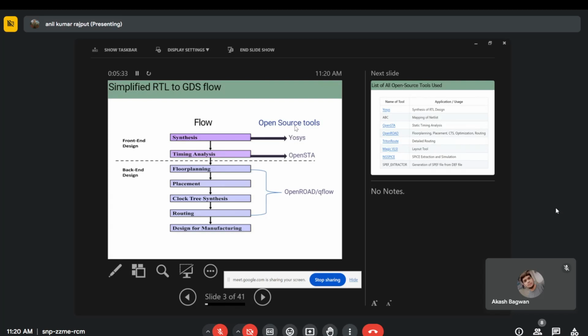After that, we use a tool. There are two tools basically, OpenROAD or Qflow. Today we will demonstrate Qflow, in which we perform the floor planning. Like that, you see this all. So there is a placement, there is a floor planning, how much size of all that. The same way, we will floor plan our IC. What is the width and height of our IC?